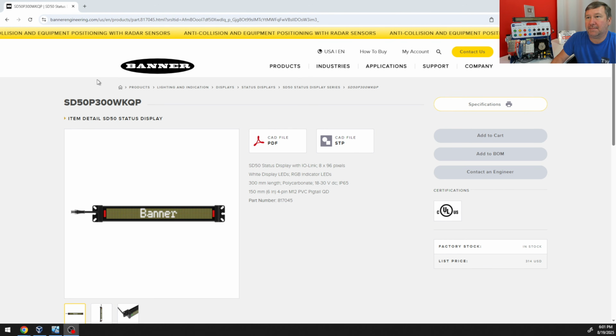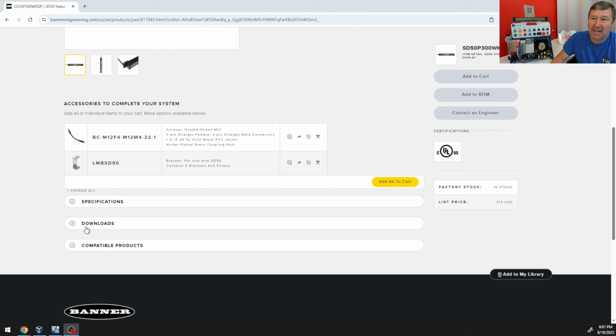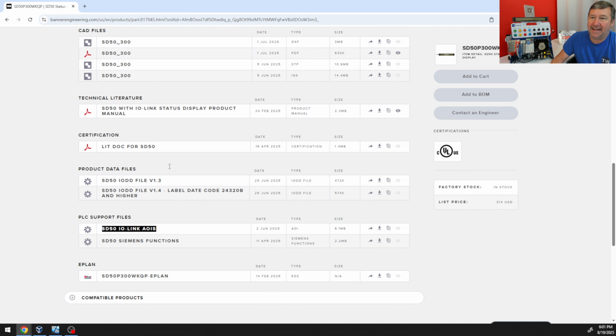So I've gone to Banner's website and went to the SD50 status display. And if I scroll down just a bit, then we have downloads. And down in there, we're going to find the SD50 IO-Link AOI. And this is what we're going to use in Studio 5000 to control this. So I'm going to go ahead and download it.